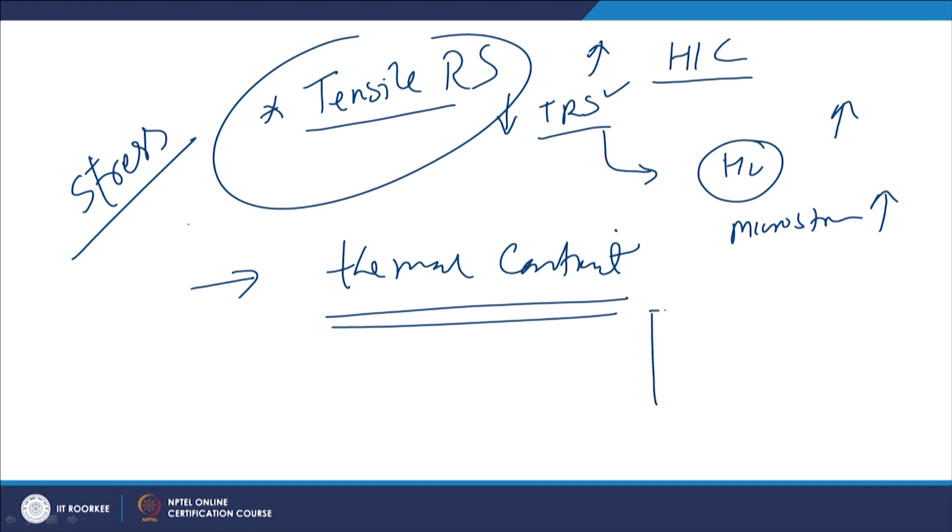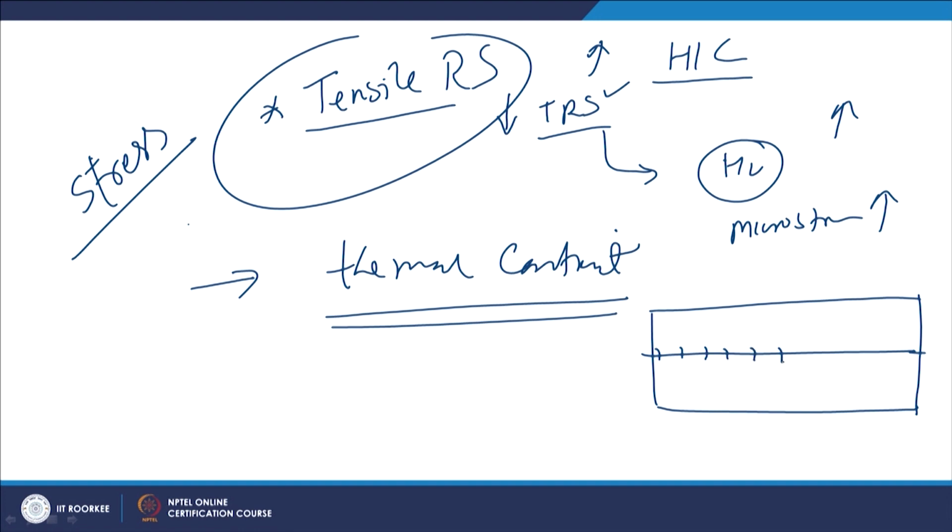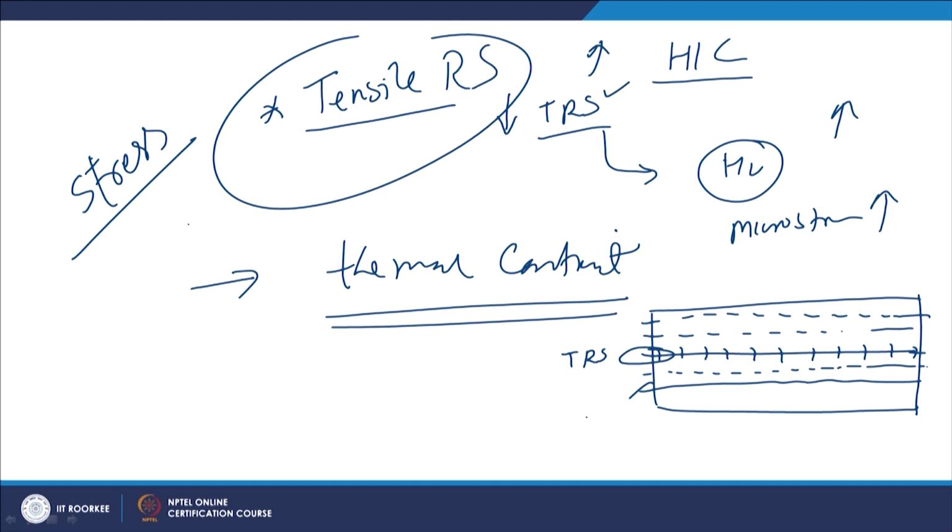So, wherever the maximum contraction is restricted, that maximum contraction restriction is observed in the weld zone. So, this experiences the maximum tensile residual stress, while the zone in vicinity of the weld metal will also be having some amount of the tensile residual stresses, and thereafter the balancing residual stresses are also developed, which will be on both the sides of the weld metal, and these will be in form of the compressive residual stresses.